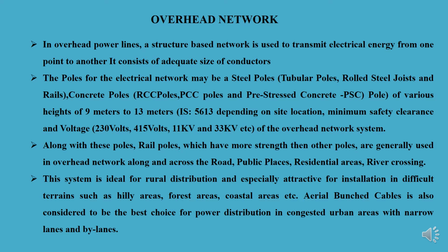If it is across the roads, or in public places like schools or hospitals, we have to take more and more precautions in an overhead network system. Safety is important, so in those particular areas, we have to use the rail poles. It may be a residential area, or river crossings.